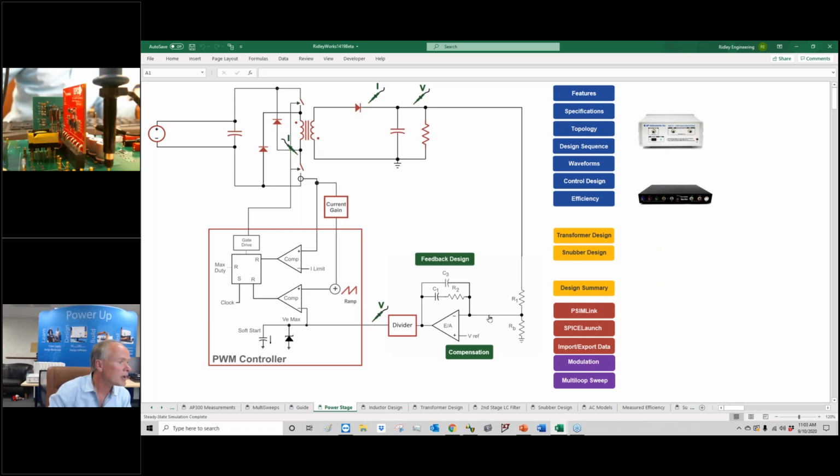Okay, somebody asked, why do we check the input inductance but not the output inductance? Well, we always check the inductance on the highest turns count winding, because that's where you've got the most resolution. So if you've got a step down transformer, you just measure it on the primary. If I measured it on the secondary, it would be the same value divided by the turns ratio squared. So you don't need to measure both. You only need to measure one. So we measure the one that is the bigger value and the easiest to resolve. So it's just redundant to measure from both sides of the winding.